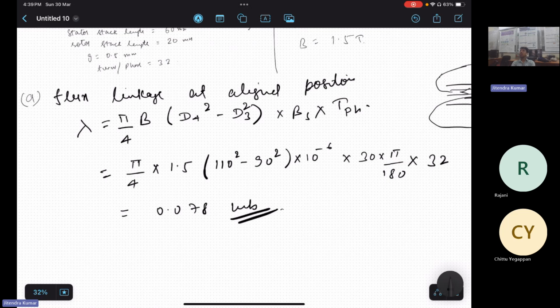Suppose you can go up to 0.3 mm of air gap, and you make one machine with a single air gap of 0.3 mm and another with a double air gap of 0.3 mm each. The effective air gap would be 0.6 mm. Though you are reducing the flux path along the axial length, you are also increasing the air gap, and the air gap requires the majority of the MMF compared to the core. So that's one thing to think about.